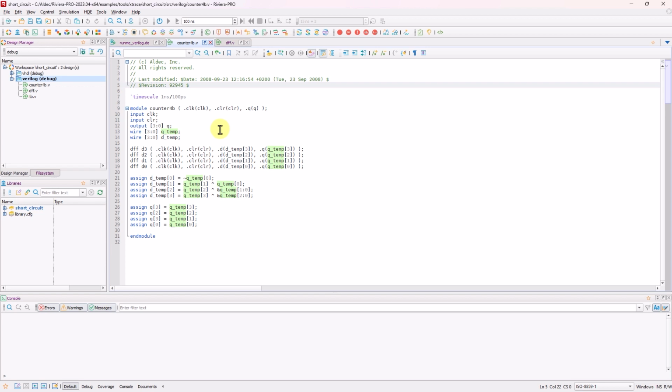My name is Chantel, and I'll be going over how to use Xtrace with Advanced Dataflow. Xtrace is a command used to create a report for whenever an unknown value occurs during simulation. It can track X values, U values, don't cares, and any other values that you specify. When an Xtrace report occurs, you can cross-probe with the Advanced Dataflow tool to bring up the Dataflow window and get a visualization of your simulated model at the current simulation time.